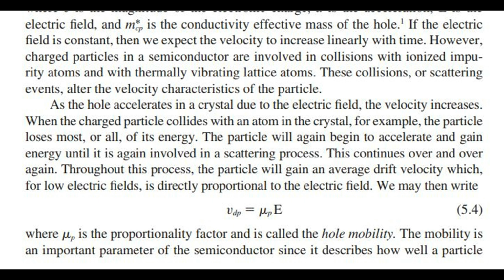As the hole accelerates in a crystal due to the electric field, the velocity increases. When the charged particle collides with an atom in the crystal, for example, the particle loses most, or all, of its energy. The particle will again begin to accelerate and gain energy until it is again involved in a scattering process. This continues over and over again. Throughout this process, the particle will gain an average drift velocity which, for low electric fields, is directly proportional to the electric field. We may then write vdp = μp E, where μp is the proportionality factor and is called the hole mobility.